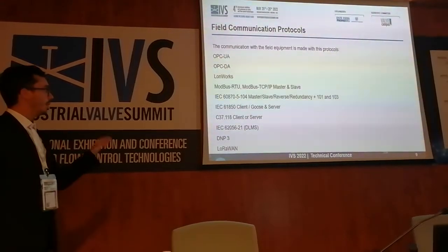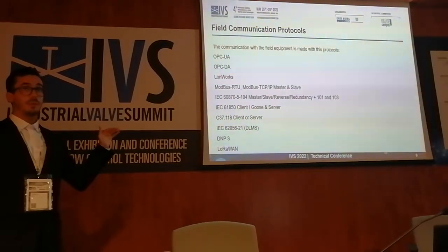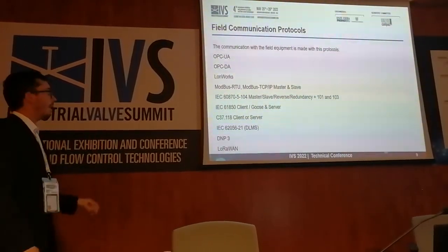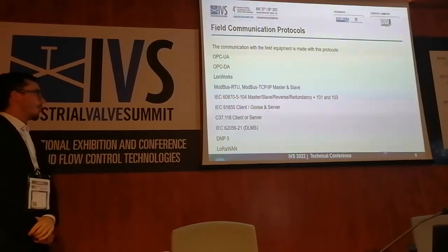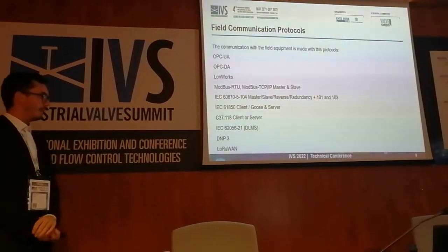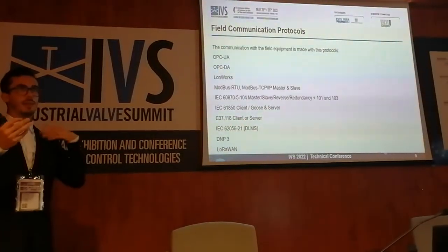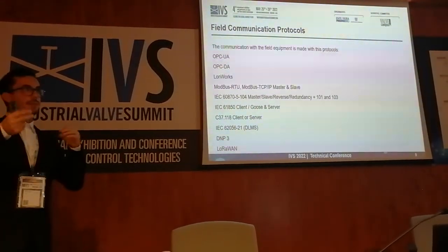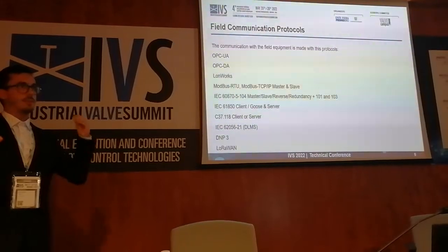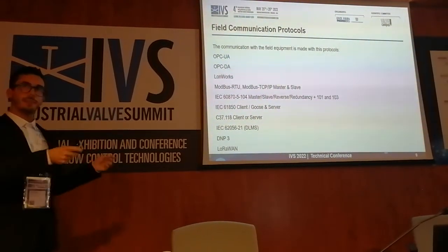IEC 62351 as well. This protocol is used for electrical communication, especially in substations. And then we have other protocols, for example, DLMS, M-Bus, and LoRa for the IoT. We use this one to provide remote information from the plant to the RTU.